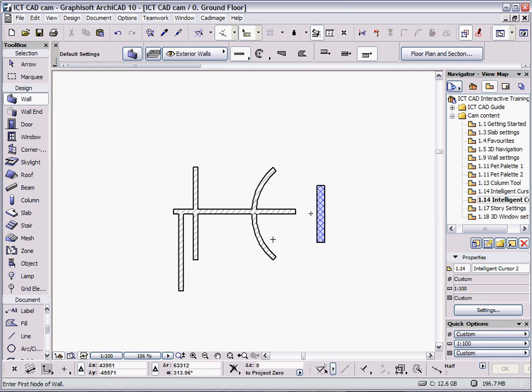Some of the other symbols that we see, first one is the trim command, and there's various ways of accessing trim. There is a trim shortcut on the toolbar. If I click trim, come across into this edge between these 2 pieces of wall, there's a pair of scissors appear, and if I click the mouse, that trims out the wall in the middle. The next one that's visible is the eyedropper, and this allows me to pick up parameters. So what I could do is pick up the parameters of this blue wall, thicker wall, like so, and then go to the inject symbol, inject parameters into that piece of wall, and that just transfers the parameters between the 2 elements.